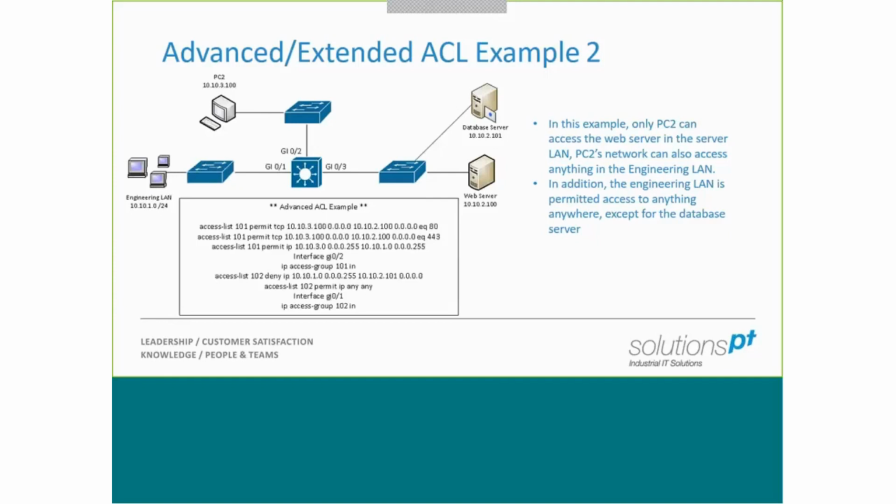Now, we come across situations on sites where the OT engineers don't own the layer 3 devices. So what are the implications there? By layer 3 devices, I'm implying that that's where most of these ACLs will be set up. Generally speaking, they are, yeah. And there are a couple of ways around that. There are scenarios where we may want to use a transparent firewall, or even talk to the IT department. I mean, you probably won't get very far, but in an ideal world, you'd have a nice discussion with the IT department and tell them what you want to implement, but in my experience...